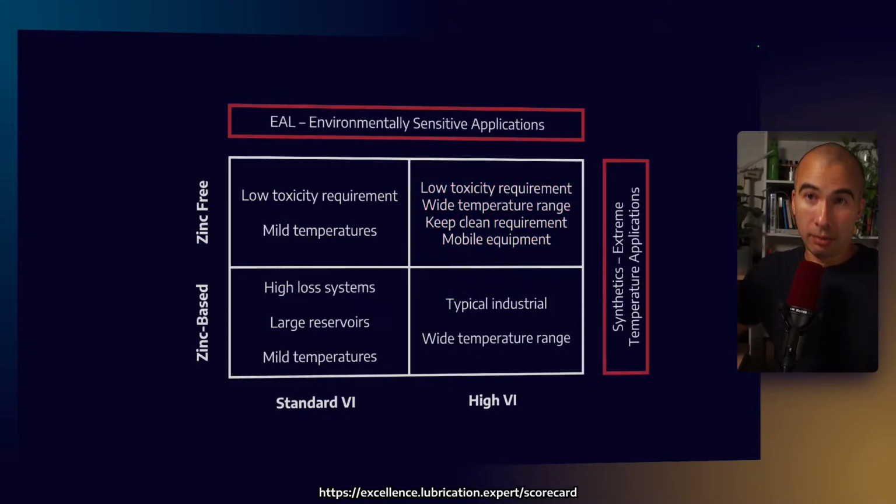All right, separate to that, we also have the environmentally aware lubricants, right? For environmentally sensitive applications, they tend to be based on synthetic esters. And then we have the full synthetics, which are for extreme temperature applications. Think about wind turbines in Arctic conditions, for example, which might need something with very low wax formation at low temperatures, and so a very, very low pour point.